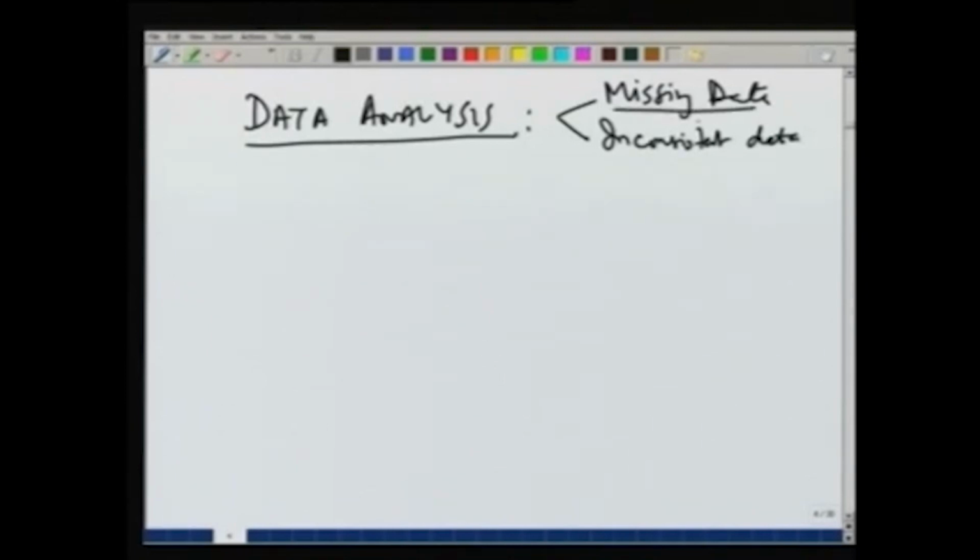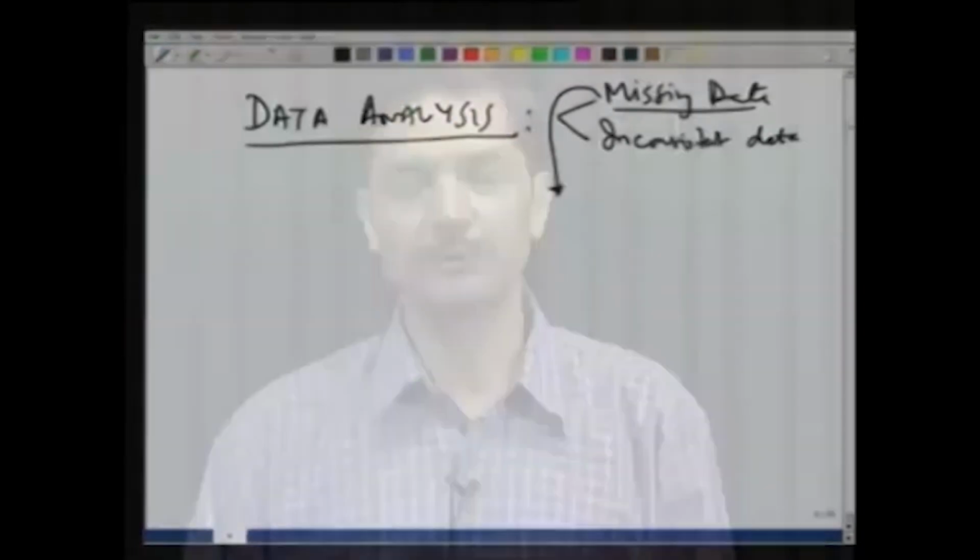Missing data, we saw that there may be various reasons for data being missed, but if there is missing data, we can use the average of nearby rain gauges and assume that the missing data relates to those values. For example, we can take the mean of the values at the corresponding stations, but if the rain gauges have very different normal precipitations, then we can take the average of the precipitation divided by the normal values.